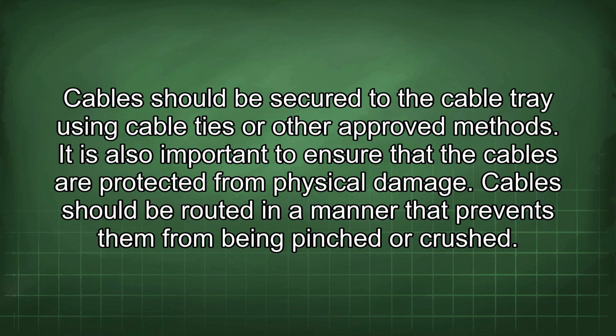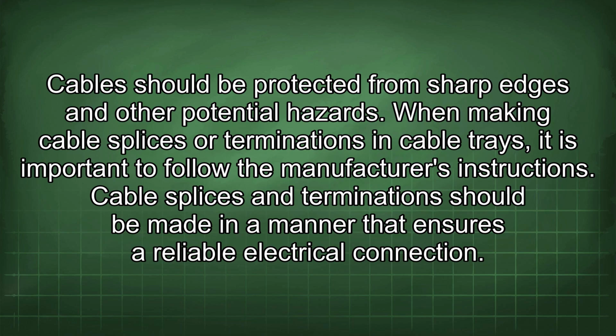It is also important to ensure that the cables are protected from physical damage. Cables should be routed in a manner that prevents them from being pinched or crushed. Cables should be protected from sharp edges and other potential hazards.